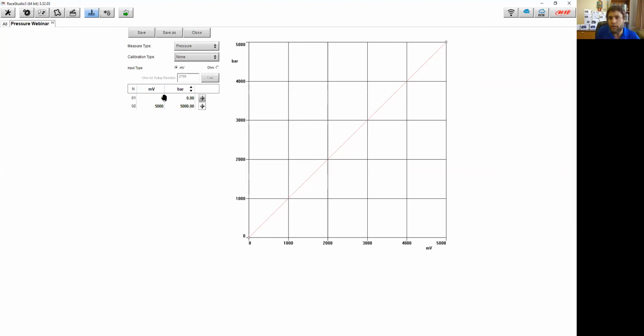And this is something that I think is going to help a lot of people. Your typical pressure sensor is going to be 0.5 volts at the bottom of its range. 0.5 volts is 500 millivolts. So we're going to put in that 500 millivolts. Yeah, everything in AIM is always in millivolts. Right. And you can see it's labeled here, millivolts, milli being 1,000 per volt.